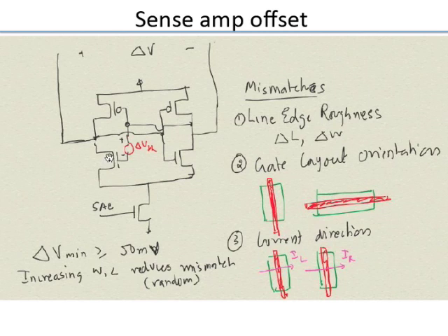As we said in one of the earlier lectures, all the design parameters are basically random variables: width, length, threshold voltage, substrate doping, etc. Because of that, you will always have a mismatch. Two transistors will never match perfectly. That mismatch has a systematic component and a random component. A systematic component means you can predict what the mismatch is, and you can do corresponding things to reduce it.